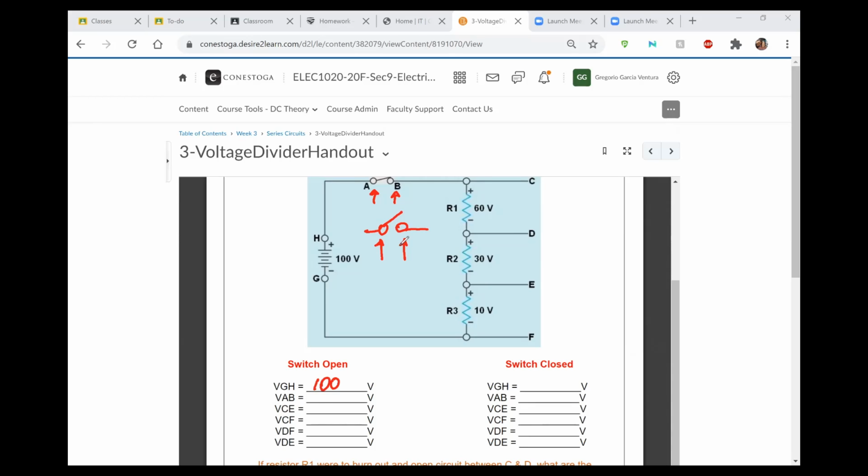Yeah, we hear you. What are you asking? The question was, if we use an ohm meter and measure the amount of ohms across an open switch, how many ohms? 100? If we measure the ohmic value of an open switch, how many ohms do you think we'll get? OL. Perfect.